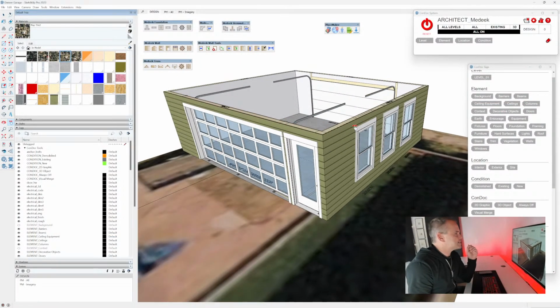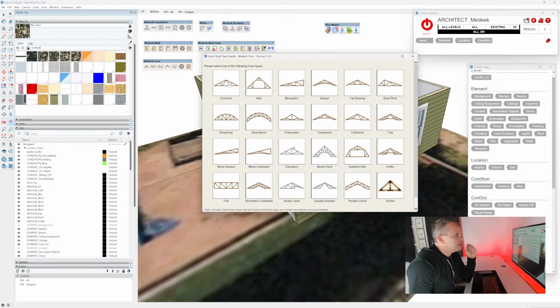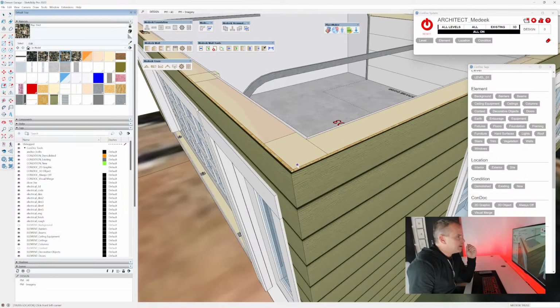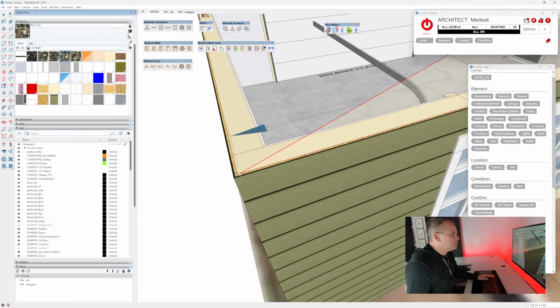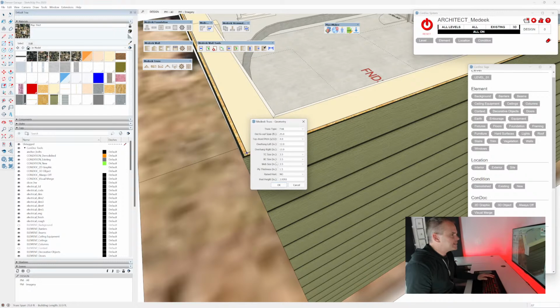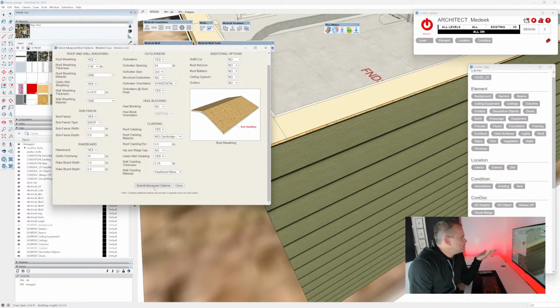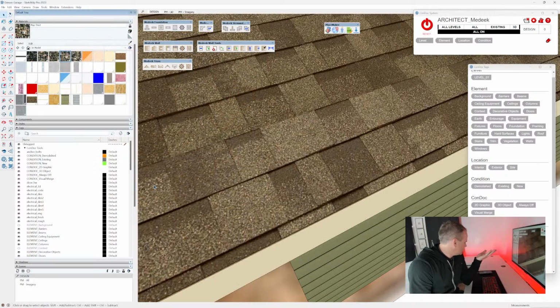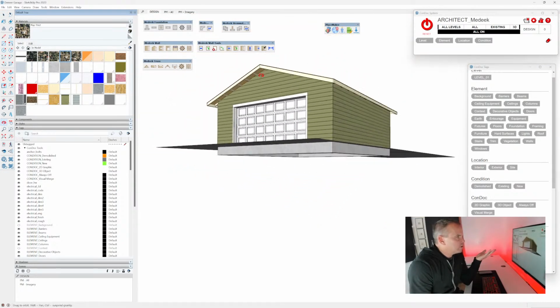All right, so our last Medeek tool set here will be to add a common truss assembly. Then I'll zoom in and make sure I go from the outer edge of my wall to this wall, and then we'll scoot over here like that. All right. Again, I tend to just use the default settings. I'll say okay, okay, and let's submit all that. And now we've got a roof, okay?